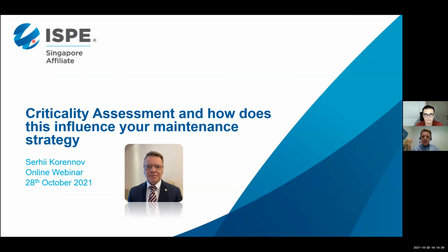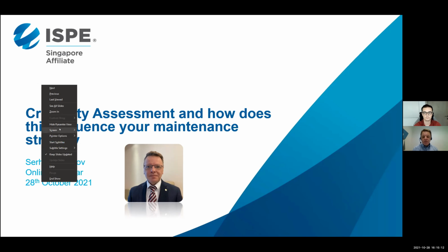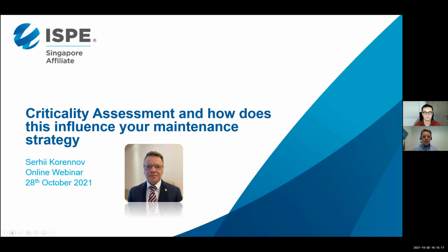We want to optimize, meaning that we want to find the right amount of maintenance that is not too low and not too high. Because it's not only about the costs, actually. Yes, having too little maintenance would increase the risk of the instrument failure, but having too much maintenance operations in the field, meaning that you access the instrument, you touch the instrument, you perform various operations, and every approach to the instrument may bring some elements of risks as well. So it is very important, both from the risk management point of view, as well as from the cost management point of view, to optimize our calibration activities.